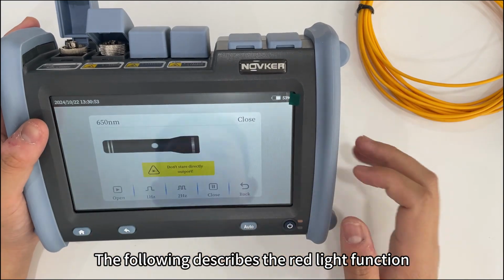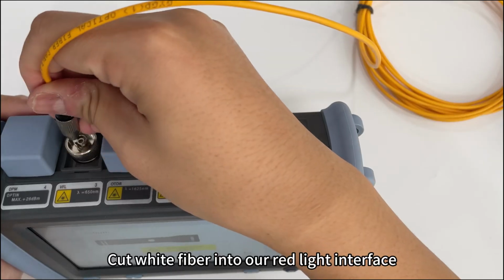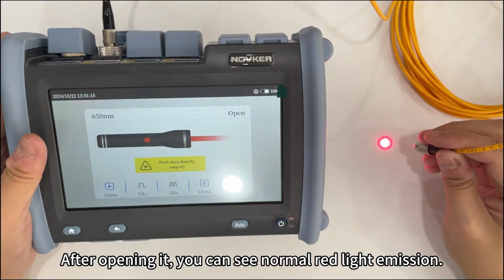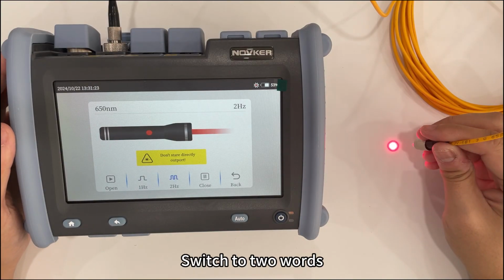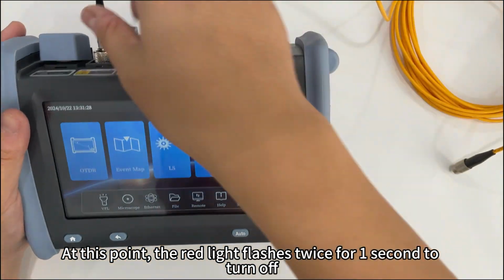The following describes the red light function. Plug the fiber into our red light interface. After opening it, you can see normal red light emission. Switching frequency. At this time, the red light flashes once every 1 second. Switch to 2 times. At this point, the red light flashes twice per second.